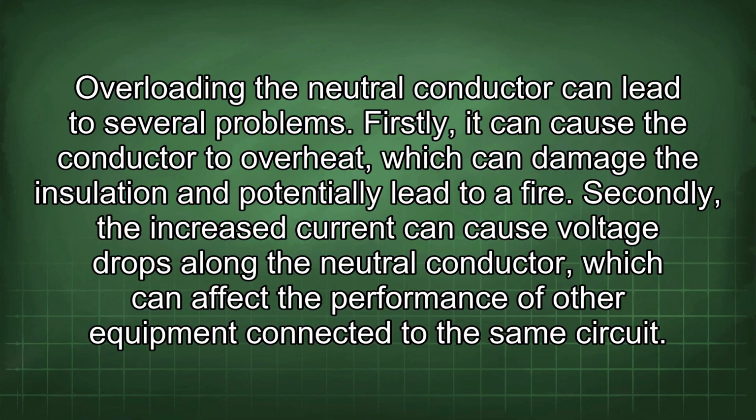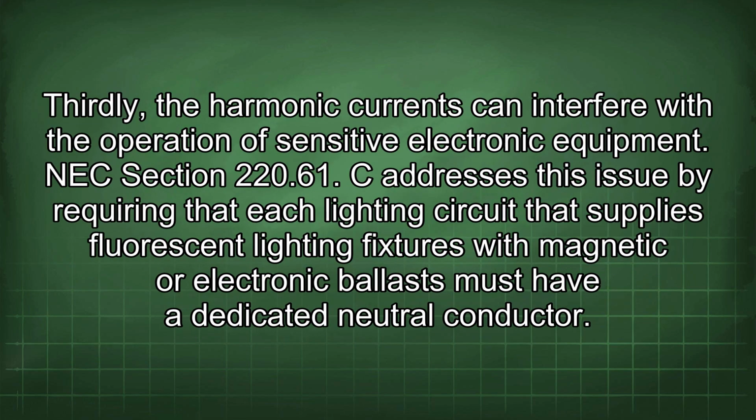Firstly, it can cause the conductor to overheat, which can damage the insulation and potentially lead to a fire. Secondly, the increased current can cause voltage drops along the neutral conductor, which can affect the performance of other equipment connected to the same circuit. Thirdly, the harmonic currents can interfere with the operation of sensitive electronic equipment.